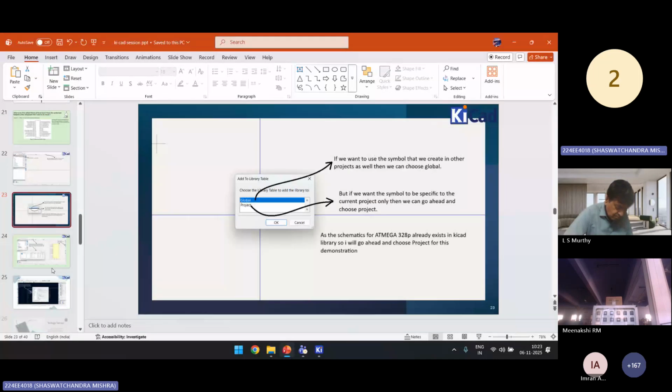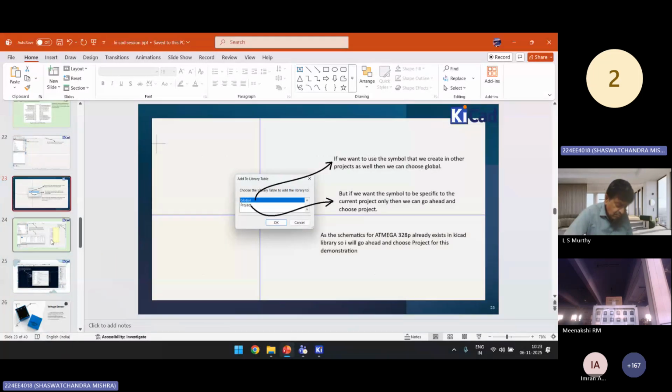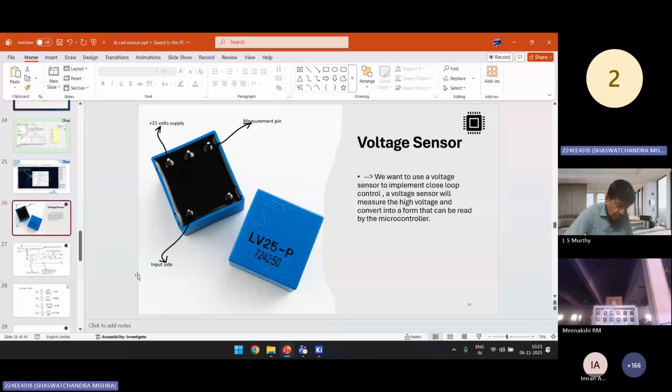So up until this, we have seen the buck converter. We designed the gate driver circuit. Now, here we are giving 0.5 duty cycle or any other duty cycle for that matter, and we are driving the buck converter, right? We gave 0.5, the voltage is cut in half. We gave, let's say, 0.25, voltage is cut to a quarter.